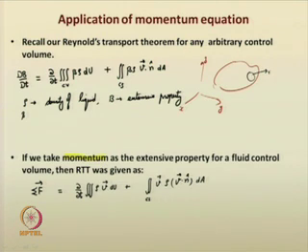area if you select. Say if I selected this particular arbitrary area, the unit outward normal vector. Say if the area was like this here, then the unit outward normal vector would have been like this. So, based on the control surface location, it gives the sign or the direction of that outward normal vector of that particular area.